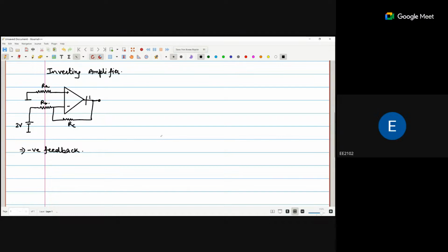Basically, break this one, increase the voltage, apply the incremental voltage. When it is multiplied with the negative sign, it will be downward. Okay, so we are getting the 180 degree phase shift. So first you have to ensure whether your feedback is positive feedback or negative.